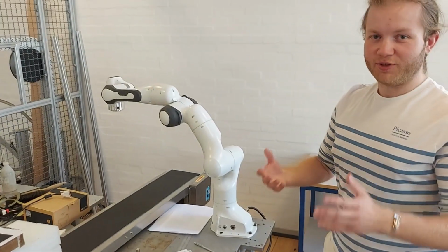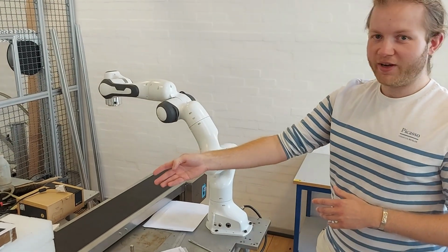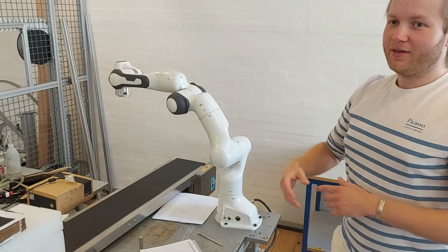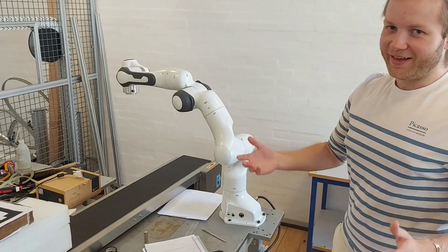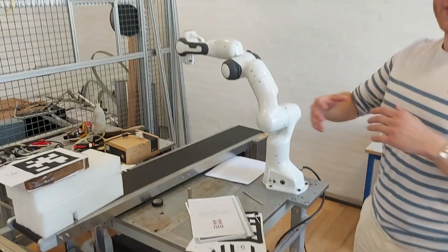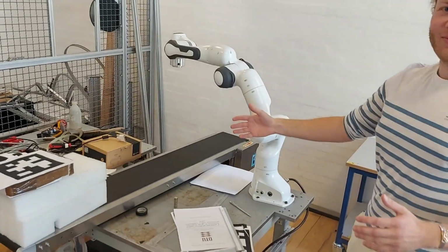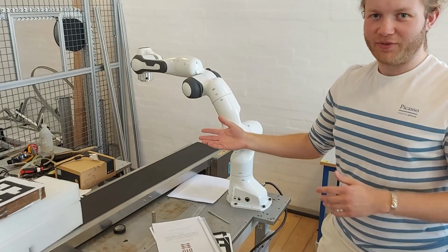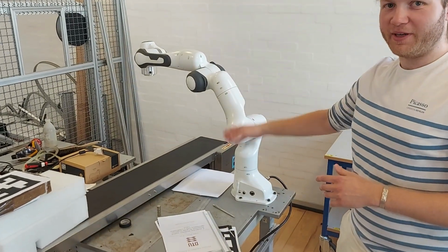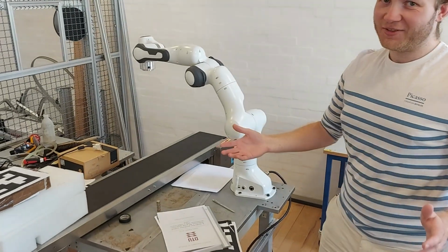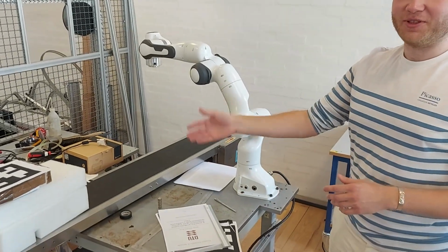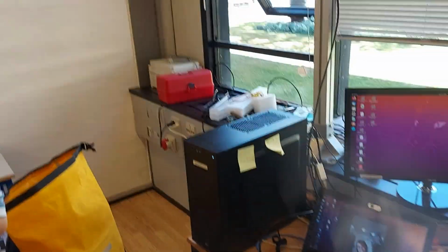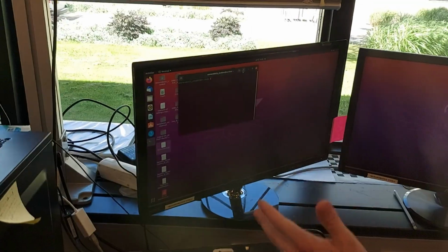This transformed AprilTag location is then passed on to a predictive Kalman filter. Then, because the predictive Kalman filter generates a very long matrix of predicted poses, but I don't have a path planner, I'm just selecting a specific one of these predictions to pass on to the inverse kinematics. So I have a prediction selector that chooses a specific prediction to pass on, and that is then passed on to the desktop computer.